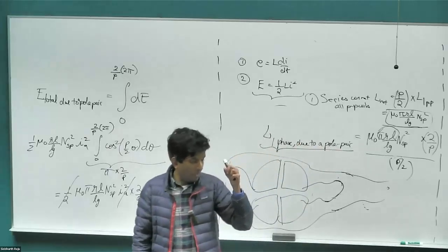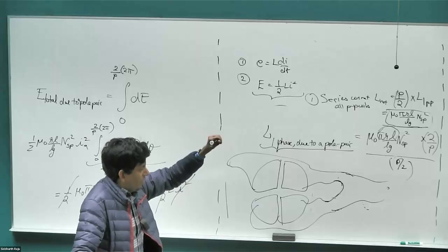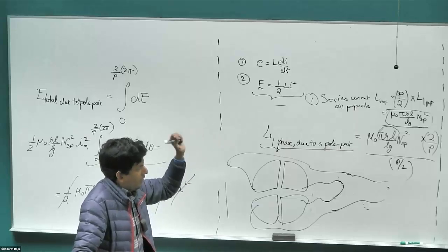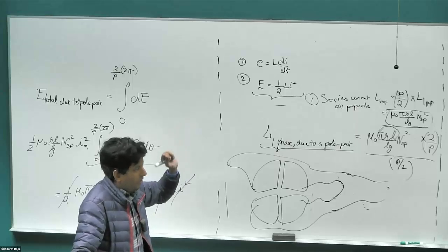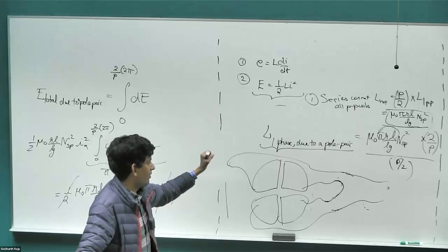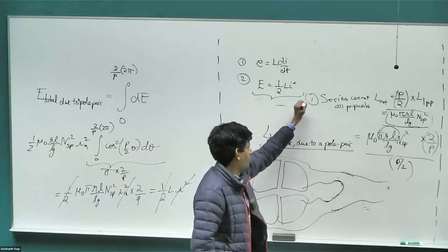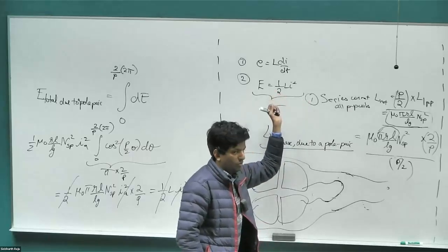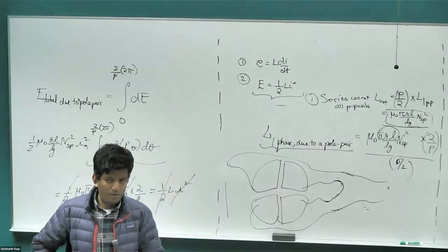Right? And the way you'll get very large voltage could either come from your grid side, or you have designed an inverter that is pushing the voltage to a very large level so that the inverter current is very small so that you have very low conduction losses. So it's a multiple decision factor that will decide whether you want a motor to have coils in parallel and have high currents, or put it in series and operate at a very large voltage, right? And depending on the speed as well, that factor will be determined. Right? Any questions so far?